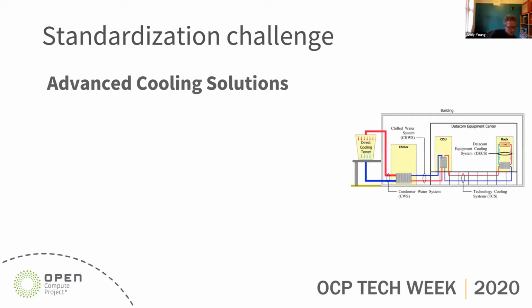So as you can see, there's the now familiar image where we see the various fluid loops with heat exchangers marking their intersection, those grey boxes, and the performance in those heat exchangers depends on the fluid type and the flow on either side. And while the efficacy of those heat exchangers is standardized for the CDUs due to them being based on mature technology, it's just a heat exchanger in a box. We understand them well. The same cannot be said necessarily for the heat transfer from the IT, which is more dependent on the particular cooling solution and the IT SKU that's applied. So interdependency and feedback occurs at the interface of the loops and the intersections.